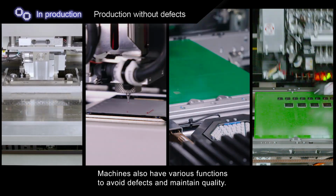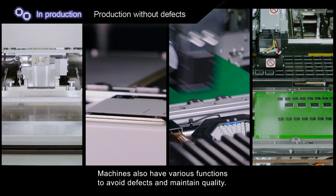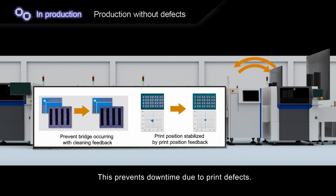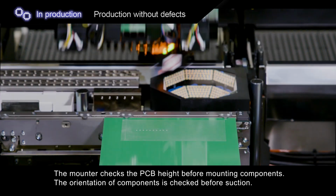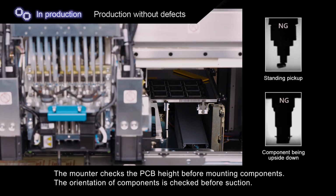Machines also have various functions to avoid defects and maintain quality. The SPI and printer are linked in order to adjust printing position, bridges, and so forth in real time. This prevents downtime due to print defects. The mounter checks the PCB height before mounting components. The orientation of components is checked before suction.